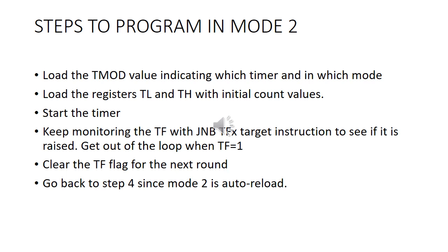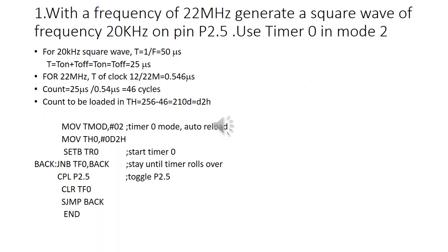Because mode 2 is an auto reload mode, we are not going back to step 2. Directly we are going to step 4, because the values will be loaded automatically since it is a mode 2 configuration. So next we'll see the problem in case of mode 2.